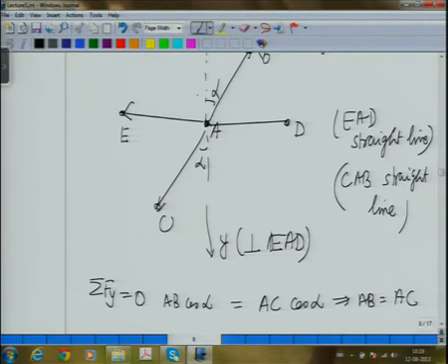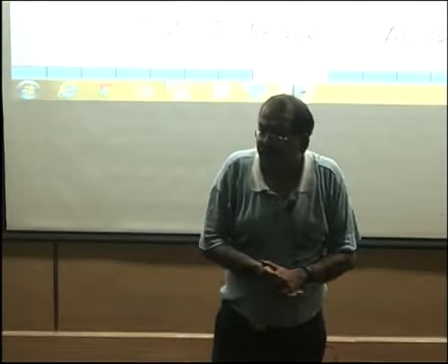Okay? Is that clear? That means the forces in members AB and AC have to be equal. Similarly, when I do a force balance along the x axis, which is along AED or EAD, I will get AE equal to AD. So, whenever I have 2 collinear members connected to 2 other collinear members at a pin, then the forces in the 2 collinear members will have to be identical, and the forces in the other 2 collinear members will also be identical.